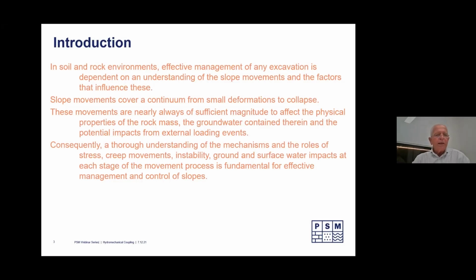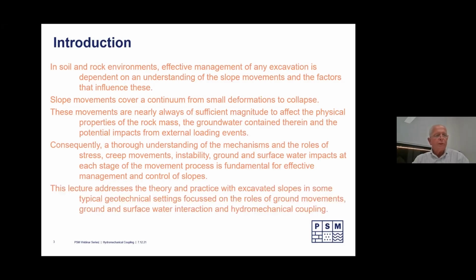So that understanding of the mechanisms and the roles of stress, creep, instability, ground and surface water, through that movement process are pretty fundamental for the effective management and control of slopes. And that's really what we're about when we're doing any excavation. We're really trying to control the slope such that it remains manageable.